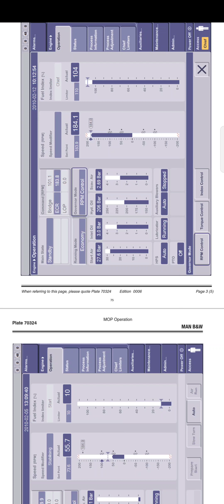Now you have the pressure indicator. The pressure indicator consists of a bar graph and a status field. Then you have the auxiliary system status indicator, and the system status indicator displays information on the operation mode of the auxiliary system controlled by the MECS. These are all indicators and do not allow changing mode or status. Possible control is made on the panels for the actual system. Indicators are HPS, hydraulic power supply unit.